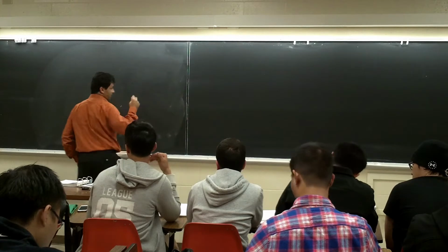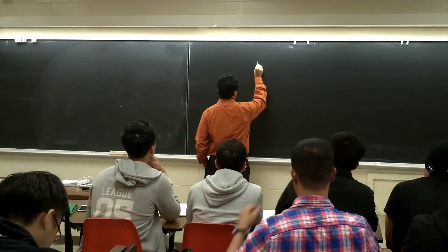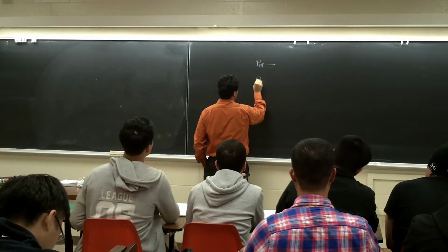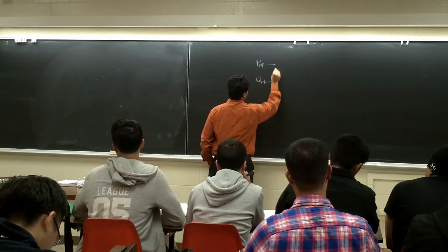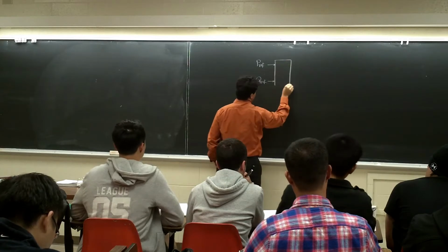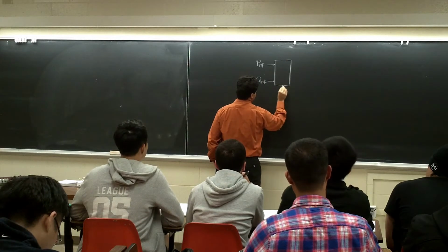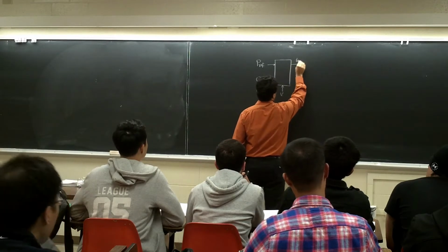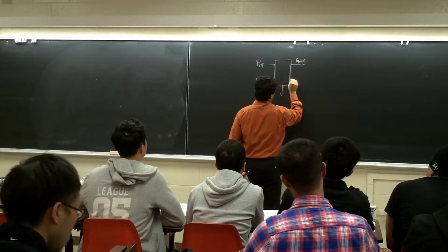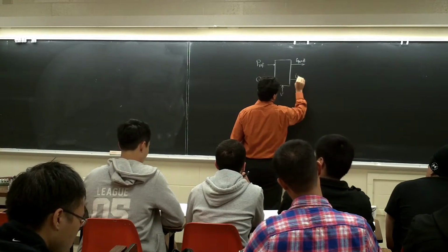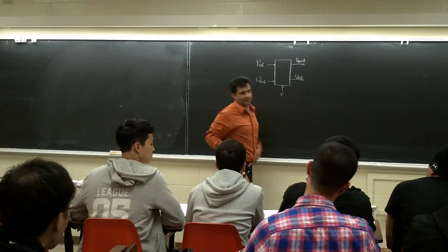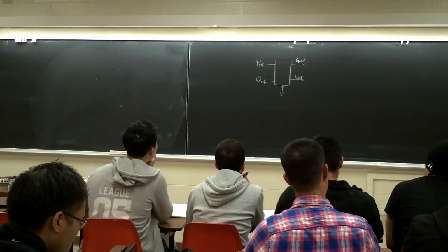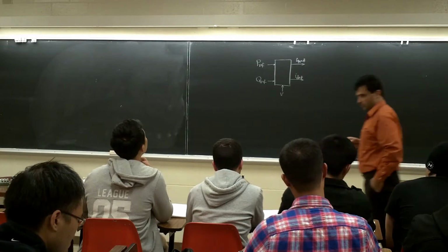If you look at it, in the middle we have a P ref, Q ref, and you have a mathematical box, and you get the V value, and you get the IQ ref and ID ref. Basically this part doesn't have any design, just some calculation. If you know how much is the P ref, how much is the Q ref, how much is the V, you can calculate ID, IQ.